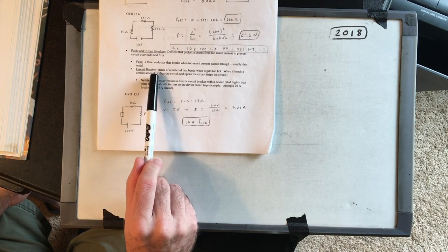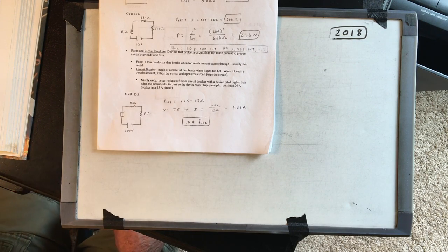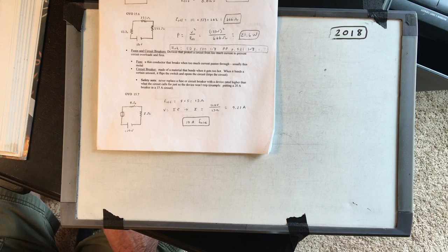With a circuit breaker, the difference between a circuit breaker and a fuse is that a circuit breaker you can reuse. So it trips. Two pieces of metal are taken apart, and so current won't flow in the circuit anymore. So if you go look in your panel box, you'll see mostly 15 amp circuits. That's for your standard lighting and receptacles. You'll see some 20 amp circuits maybe for the kitchen, and for your air conditioning unit you might see a 30 amp circuit breaker for that.